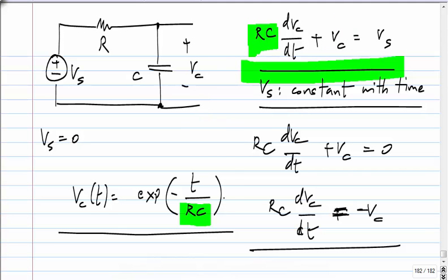So it's the same thing that appears here, right? But you have to be careful. Don't do it with 2 here or some other number there. That is not the time constant. If you normalize things so that the coefficient of this variable term is 1, then whatever is multiplying the first order derivative term, that is the time constant. Okay.